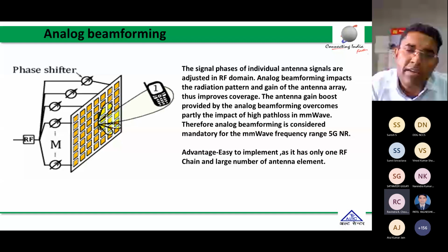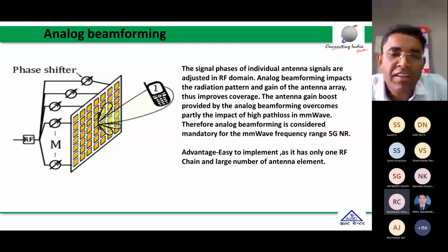So, sir, when we conduct the EMR test on, say, a 5G BTS, we have to ensure that no beamforming mechanism is on. Otherwise, at the testing location, the EMR meter is not going to measure only one beam. Actually, they are measuring the overall radiation, not a single beam.